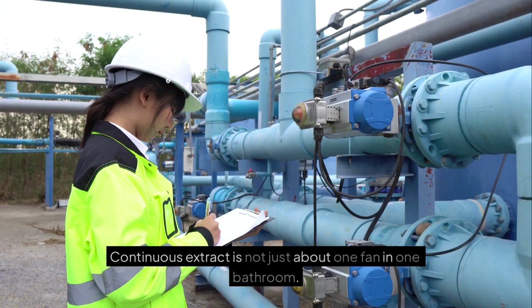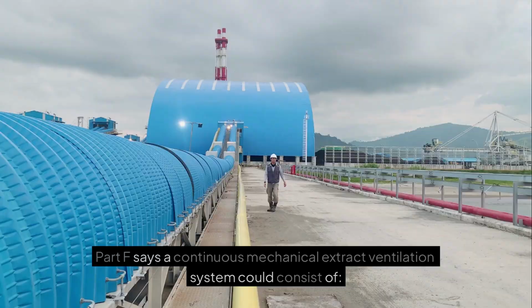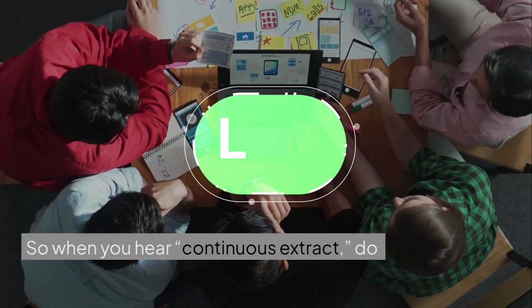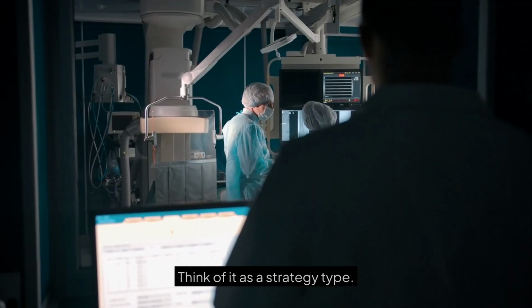That sounds simple, but the important thing is this. Continuous extract is not just about one fan in one bathroom. It is part of a wider dwelling strategy. Part F says a continuous mechanical extract ventilation system could consist of a central extract system, individual room extract fans, or a combination of both. So when you hear continuous extract, do not picture only one specific product. Think of it as a strategy type.